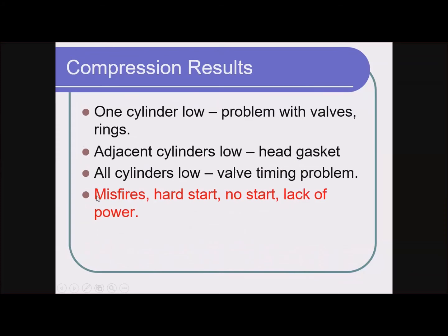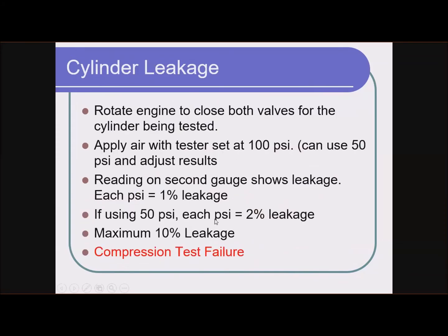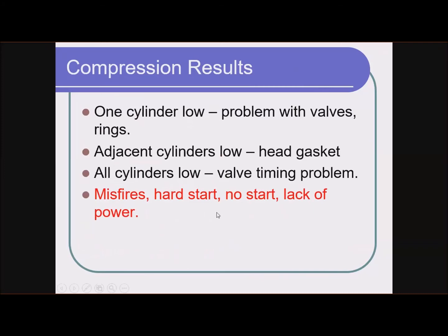Misfires, hard start, no start, or lack of power. So depending on what symptom we're trying to diagnose, we're looking for something different out of a compression test. If we have misfires, we are probably looking for one cylinder that is different than the rest. If we have hard start, no start, or lack of power, we may be looking for some sort of a problem that is connected to all of the cylinders. So think about what kind of problem that could be.